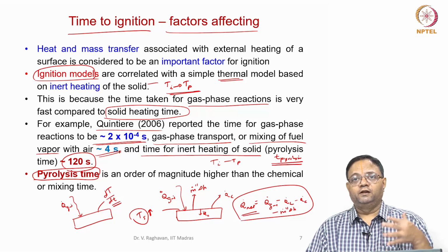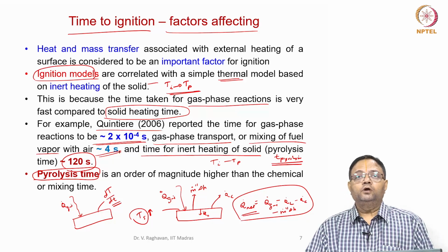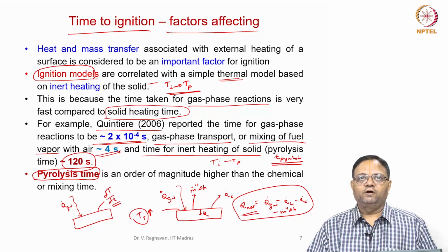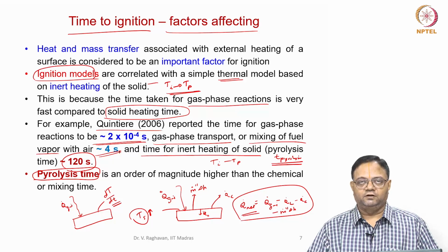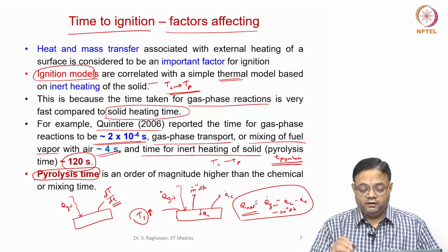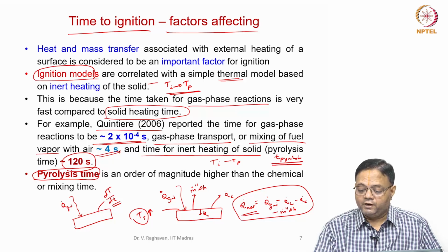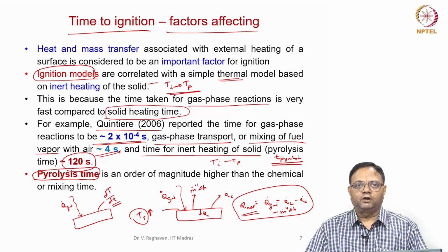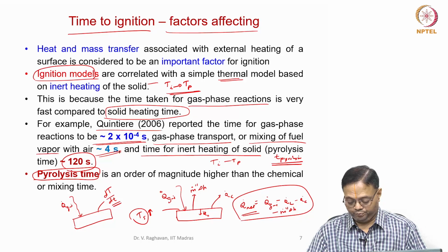Even though we have seen in liquid burning that the liquid evaporation is the time limiting, or rate controlling, factor for evaporation as well as combustion, in this case it is the time for inert heating of the solid, that is the pyrolysis time, which is important.